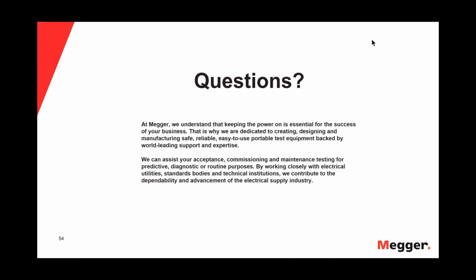Marshall, what equipment do you use in current method fault location? Well, we probably should have Henning answer this question since he talked about it, but the pieces of equipment that you would use to chase current, if you will, is you're going to have a thumper, that's your signal generator, and then your impulse detector, your galvanometer, your pickup.